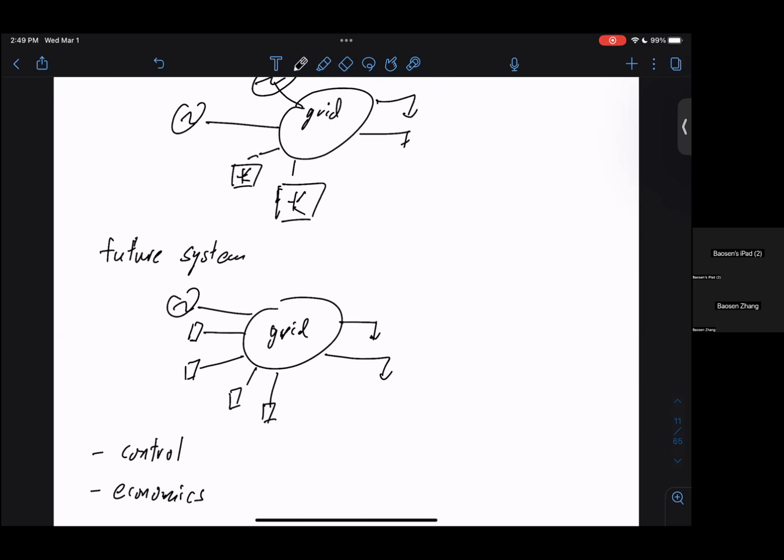Okay, so if you're solar, can you generate more power? If your frequency says generate more power, what happens there? Remember, let's say load goes up and you're solar, and you measure frequency, and it says generate more power. You may or may not be able to do that. You may not be able to get more power out of this. Compare that to a big generator: most times you can always shove in more fuel, and output will go up. It's not very efficient, but it will do something.